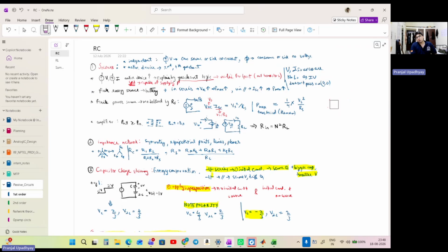Okay, this is very curious now. Why is it very curious? Because I just mentioned that for an ideal voltage source and an ideal current source, the IV characteristic for voltage will be like this, and for current, it will be like this. And when the voltage source is non-zero, and the current source is also non-zero, then their graph will not pass through the origin. Now that begs the question: is an ideal voltage source and an ideal current source a linear system?